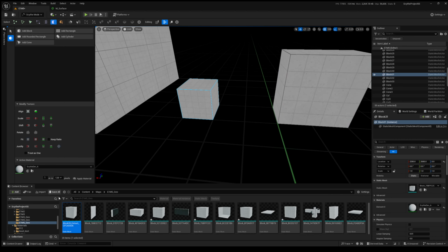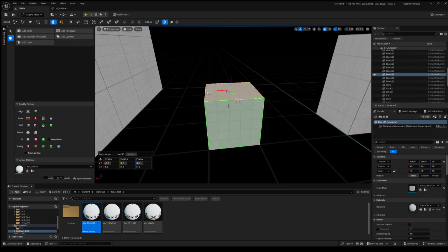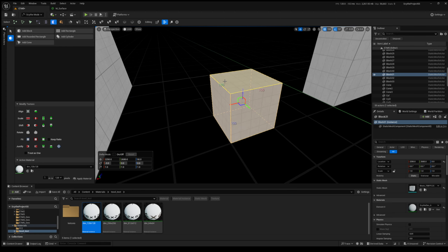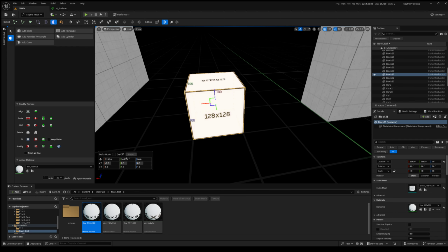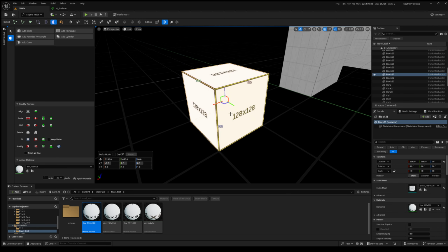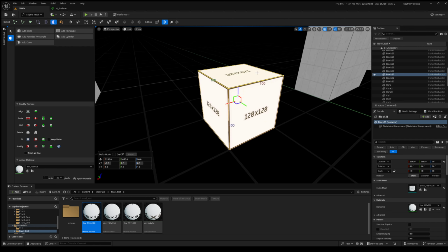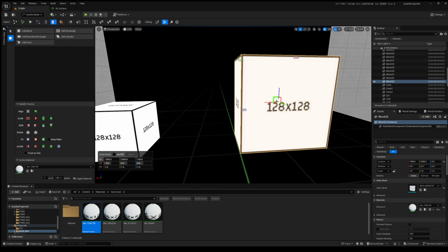I'll just go over this real quick. Texel density. This is your texel density setting right here. So 1 meter is 128 pixels for me. That's what I currently work with. You'll probably be bigger. But I'm going to select all the faces here, select one, hit Control A, and then apply material or hit Shift T. And I have this little material here that's 128 by 128 pixels. So the texture itself is 128 by 128, and this knows to fill this. I'll throw it on here just to really drive this home.